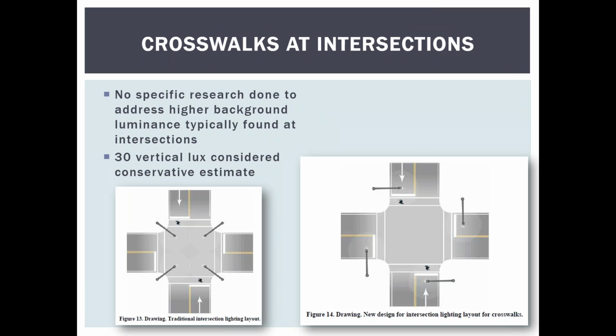The person pointed out that comparing left to right, in the situation on the right, it seems that the illumination is better for vehicles approaching the intersection, but they're concerned that after going through the turn, the lighting might drop off as they're coming around the turn, where the lighting may be lower based on where these are placed. Is that a concern with this, as opposed to the more uniform distribution of light in the left-hand example? Well, I think that again, the pedestrians in the crosswalk are backlit, and so they're not as well seen as they are in the other cases.